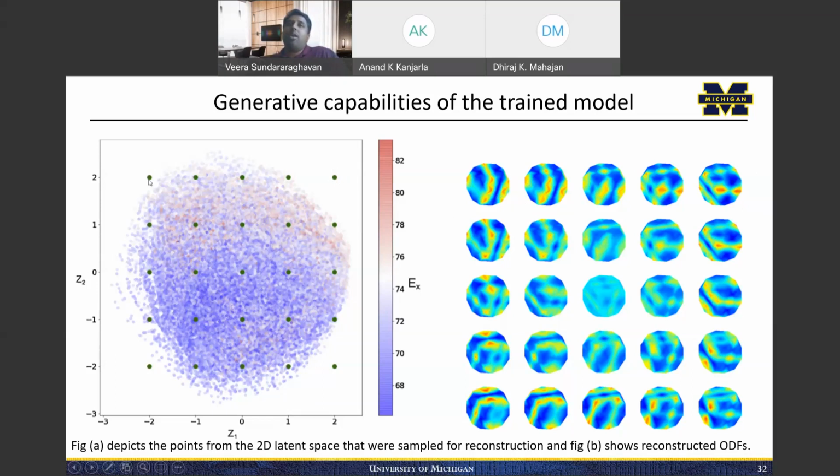The transition from the left to the right, going across, starts from a texture with a feature on this side, 2 lines, and the lines get crushed towards the ellipse. If you see 3 different points here, they get crushed towards the ellipse. There's also structure in this direction: it starts from a line, goes to a line here, and slowly transitions back to this. So it's a very cool way to synthesize these ODFs as a transition from one principal fiber component to another directly in the texture, but using a 2-dimensional space where someone can take a mouse, click on a point, identify it, move it towards the x-axis or y-axis, and identify how the ODFs can change according to a process.